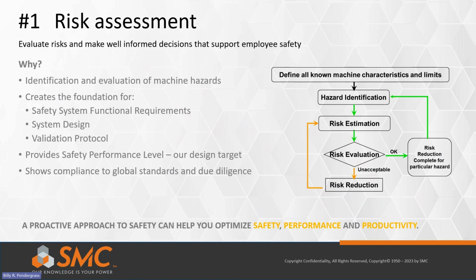The machine risk assessment identifies and evaluates hazards based off a risk scoring system. It creates the foundation for the next steps of the safety life cycle, provides the appropriate performance level, and shows the compliance to safety standards.